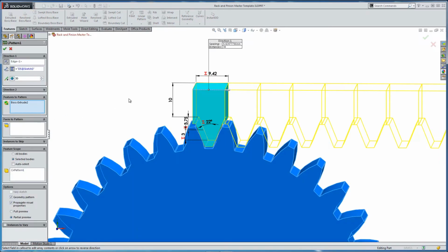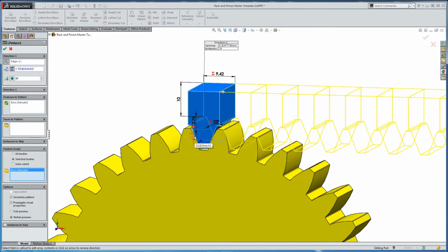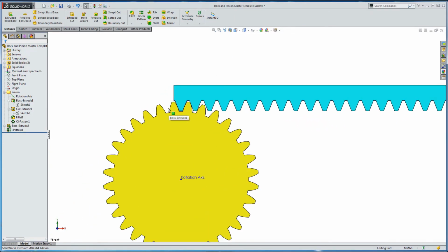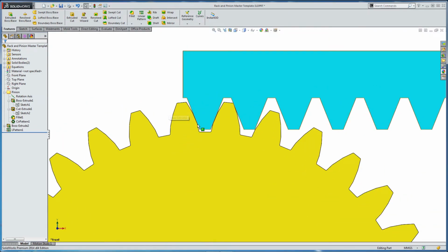So it's alarmed out. We need to go in and let it recalculate. So the links have been made. Let's say OK. Something we're not happy with in the geometry. We need to select the right bodies. We don't need to select the circular pattern. Deselect, select the right body. Check everything. Press OK. And you can see that the geometry that we wanted to merge with has merged.